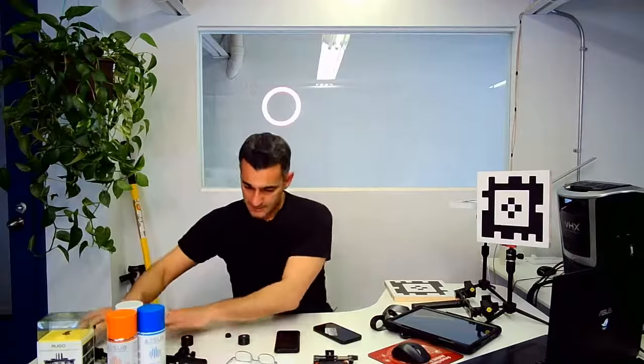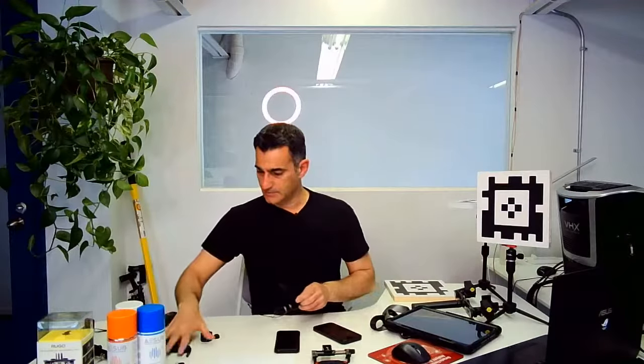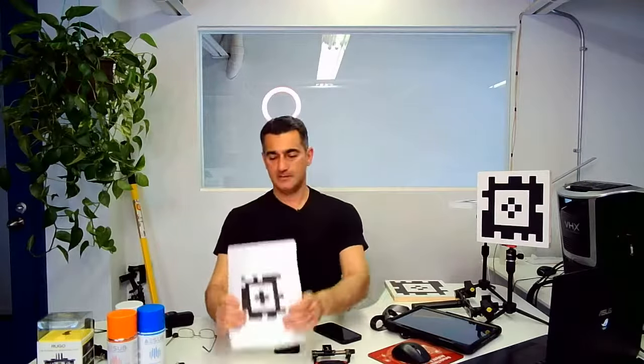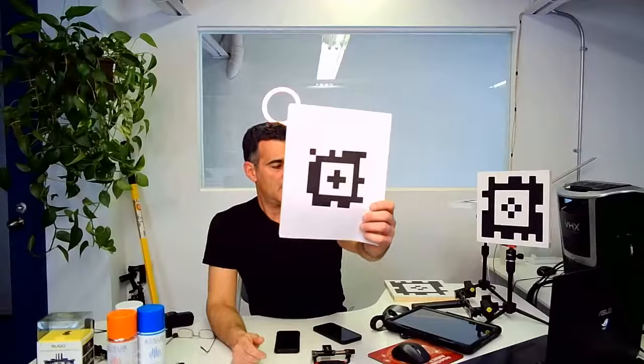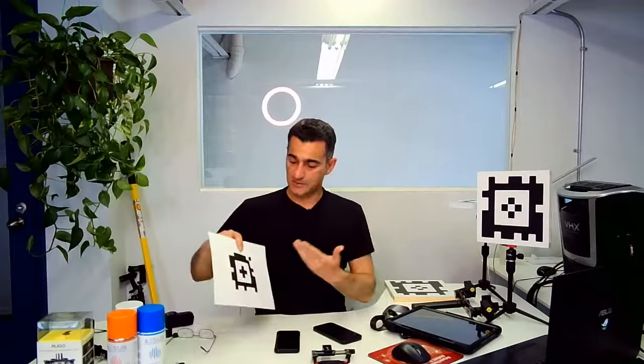I talked about all this stuff. Let me continue on here and talk about targets. These are the targets that are being used for Recon-3D, and you can print these out on A4 or 8.5 by 11. You can make them larger, you can make them smaller. The problem with making them too small is that they're not going to get picked up inside of the camera view as you're scanning. So the smaller they are, the closer you're going to have to be to them.